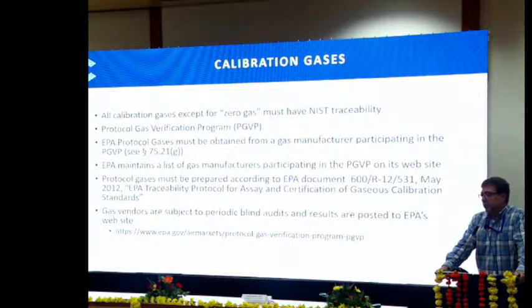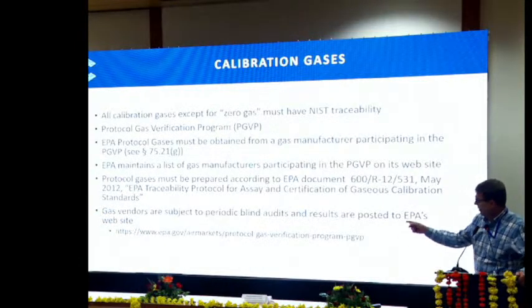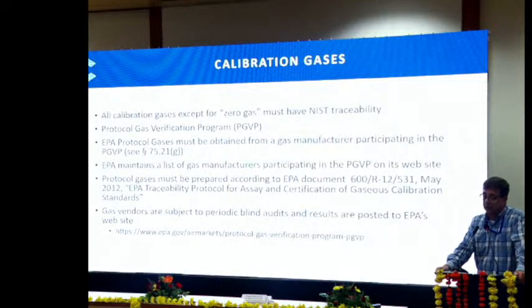Protocol gases must be prepared according to EPA document 600/R-12/531, dated May 2012, EPA Traceability Protocol for Assay and Certification of Gaseous Calibration Standards. Gas vendors are subject to periodic blind audits and results are posted to the EPA's website. You can view these results at the following link.